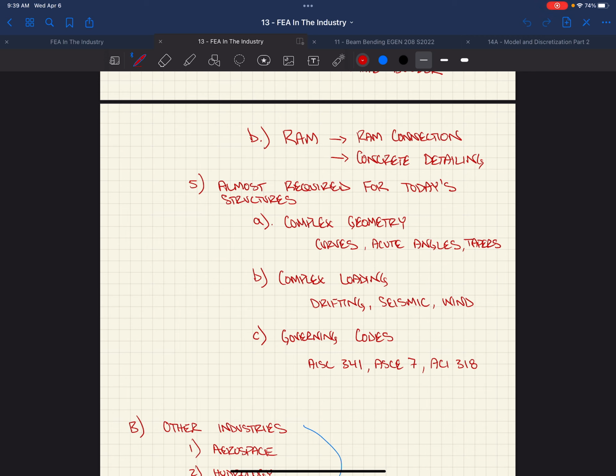You're screwed, okay? And so when you design braces, at every level, the unity on your braces should be like dialed. You do not want a brace that's at 50% unity, right? Because when you hit it with that earthquake, it's never gonna yield, right? So what does that mean? That everything else in your whole system is going to have more load on it because you're not going to dissipate any energy until something yields, right? And so I've designed buildings where everything is tight, and even the steel erectors were like, holy shit, these braces are tiny.